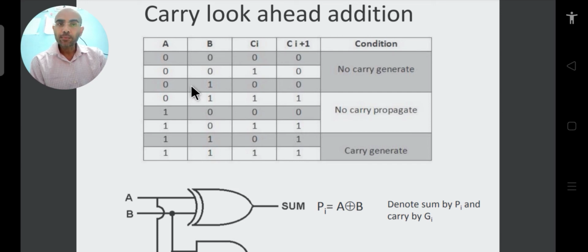In this, what we do is, this is our usual process. There are three inputs. We will implement it for a full adder. If we are able to implement it for a full adder, and replicate it multiple times, then we can make an adder or subtractor circuit of any bit length. So let's start with our full adder.